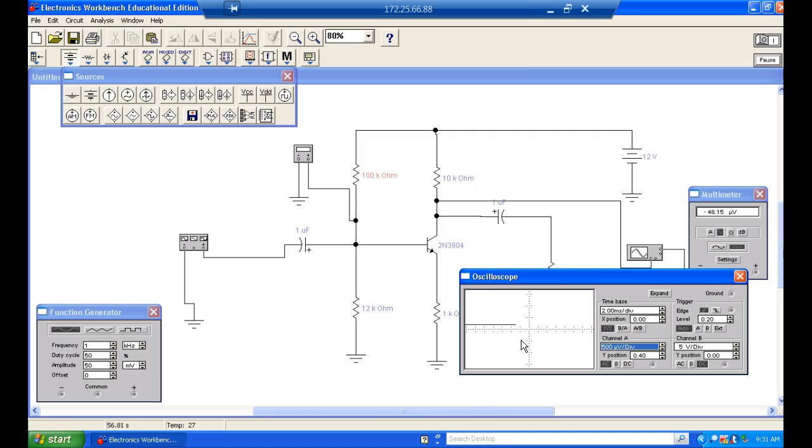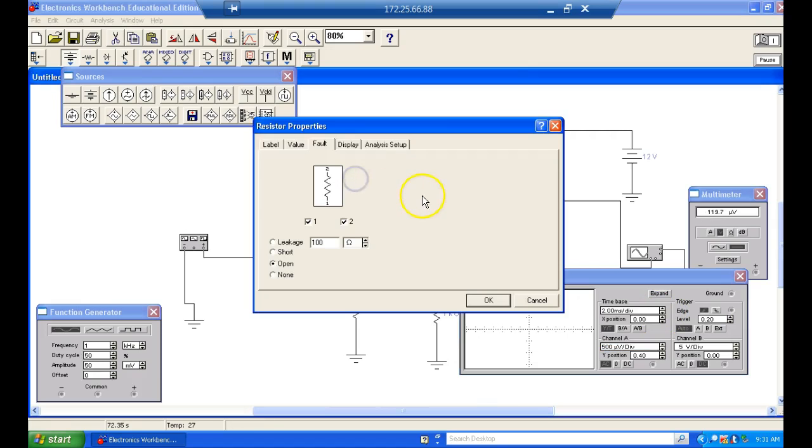So you need to know what you need to set and what you're supposed to see before you put it on there. This is a big thing that I try to preach: don't use a meter if you don't know what to expect, right? It could cause you some problems. So we did pretty good on that. So let's open this.